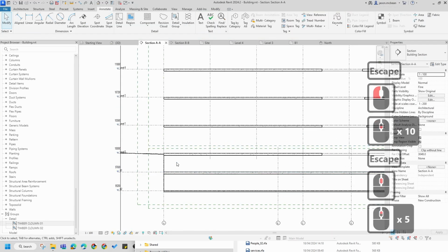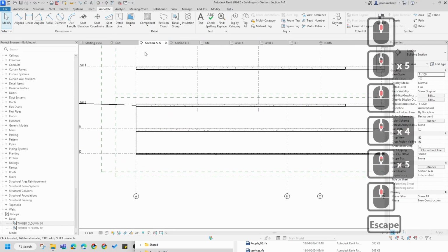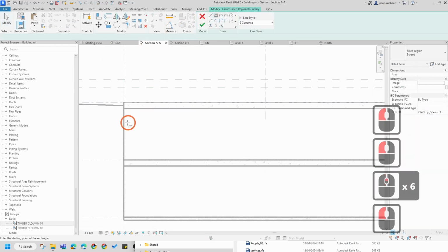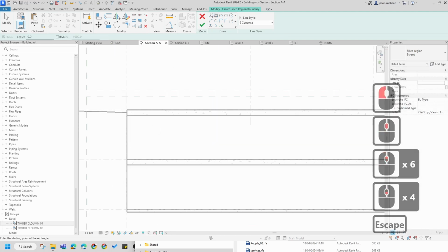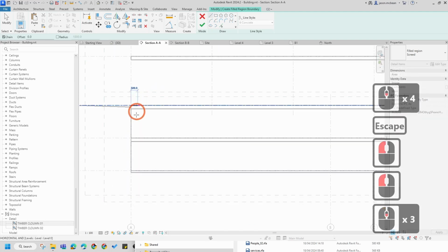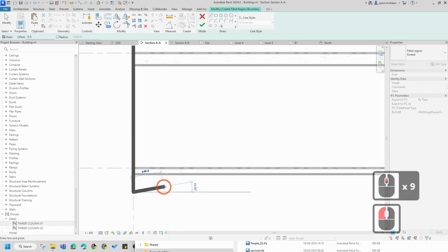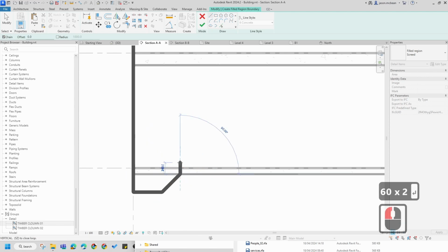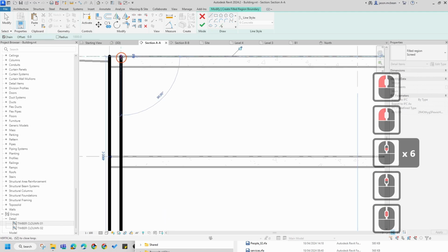Now what I'll do very quickly is I'm going to fix the concrete basement and show you how that will work. So I'm going to say fold region again. I'm going to quickly create a concrete. I'm going to just start drawing lines. So I'm going to say from there down to, okay, now we're going to take it a bit further and I'll explain. We're going to make this 600. So type in 600. You can have an angle at 45 degrees. That's fine for now. I can snap this back to there and I can draw back up and I can go right to the top just like this.